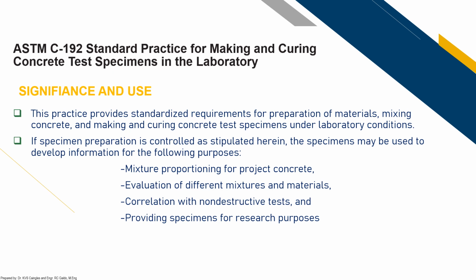If specimen preparation is controlled as stipulated herein, these specimens may be used to develop information for the following purposes. Okay, first, mixture proportioning for project concrete. Next is the evaluation of different mixtures and materials, and at the same time correlation with non-destructive tests and providing specimens for research purposes.